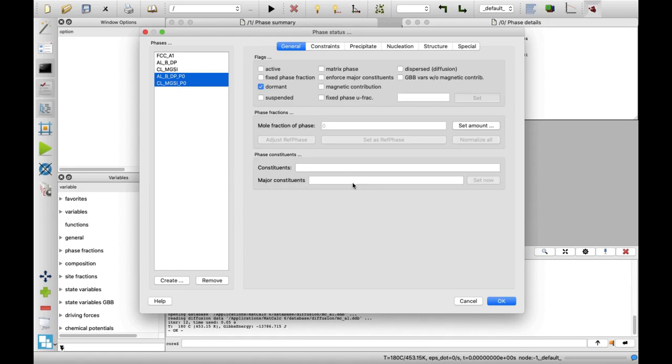Let us start with the co-cluster phase. The co-cluster phase is difficult to model properly, because it is on the border of precipitate definition. On one hand, the clusters could still be regarded as a bunch of solute atoms that come together, on the other hand they still comprise a part of the matrix. So, in our approach we treat these as precipitates. In order to represent their high number density, we have to modify the interfacial energy.